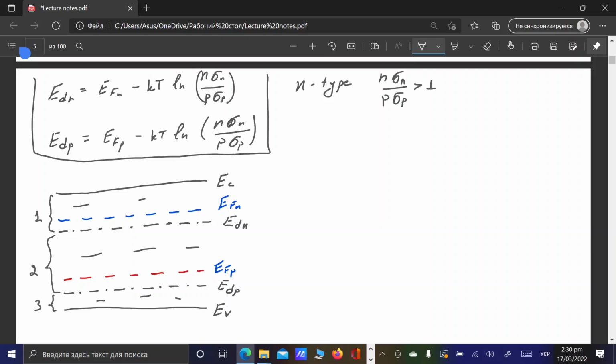We considered trap-assisted recombination via localized tails in disordered semiconductors, how we approach this issue, and also how we quantitatively distinguish between traps, localized energy levels, and efficient recombination centers. So with this, we make a transition to charge transport.